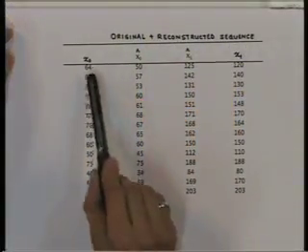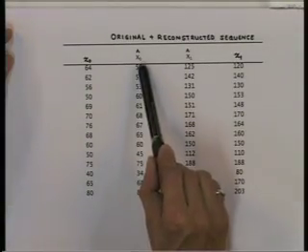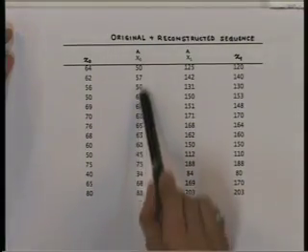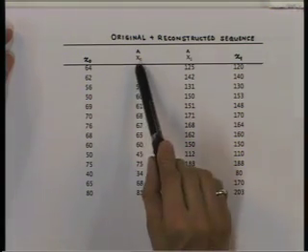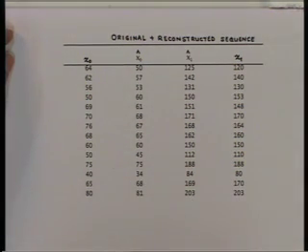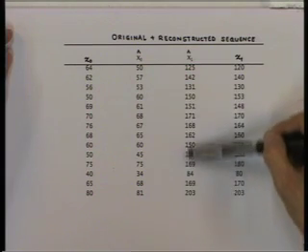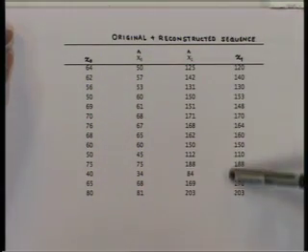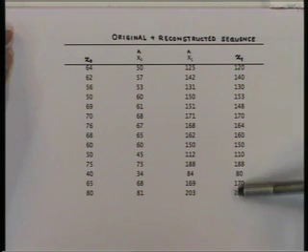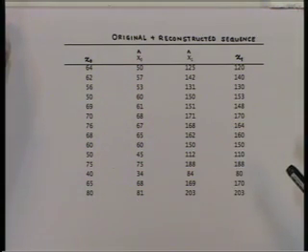And if we compare this reconstructed sequence with the original sequence, this is a table which depicts that. So, this is the original sequence and this is the approximated or reconstructed sequence after we throw away half the number of components of the transform coefficient. Similarly, this is the reconstructed second component of the sequence and this is the original second component of the sequence.